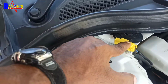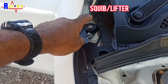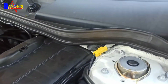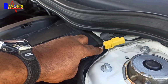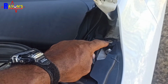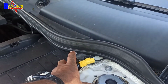Alright, so these connections come to the active hood squib. These are the components in question, one for the left, one for the right. What I'm going to do is test the connectors and do an ohms reading in the squib circuit. So let me get the multimeter connected and show you what's up.